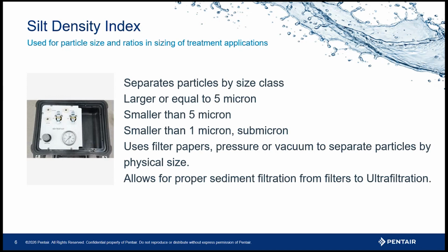Otherwise, you have to account for that, and the homeowner needs to be aware that up to this point in the home, the plumbing is exposed to this aggressive water. Air oxidation and pH modification together may be used to reduce color from metal ions. Ion exchange works well with colored waters with lower pHs because you get excellent exchange processes going on, unless the pH is really low.